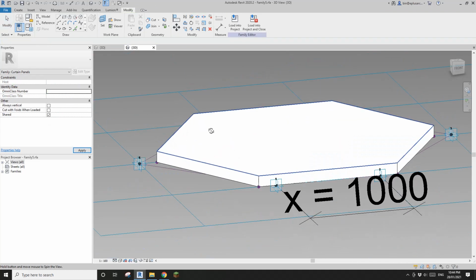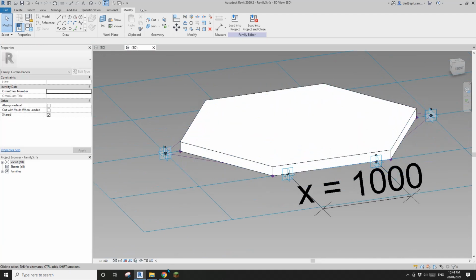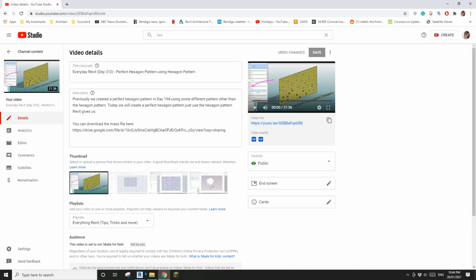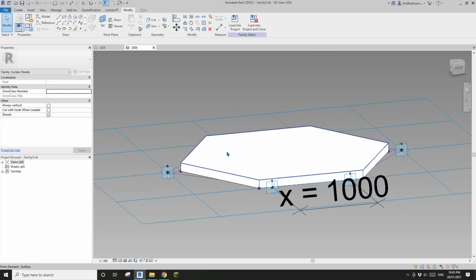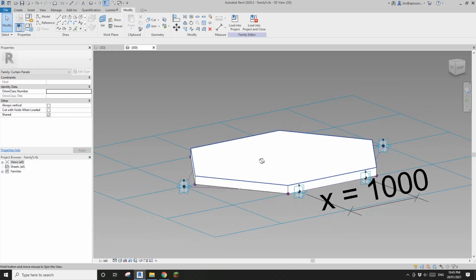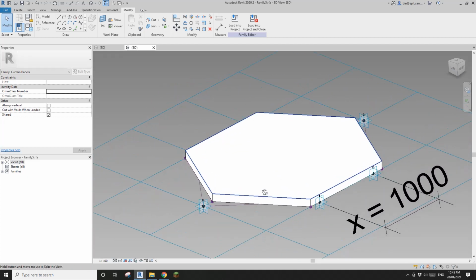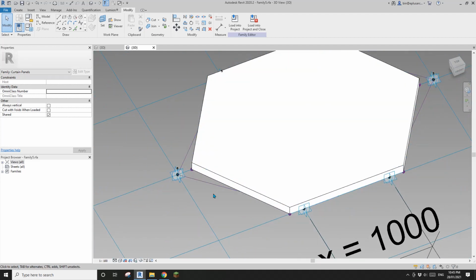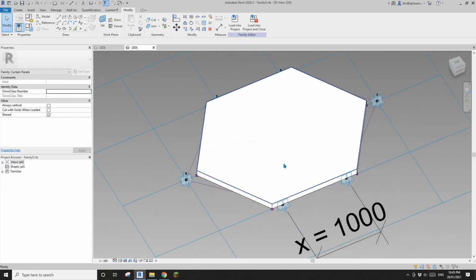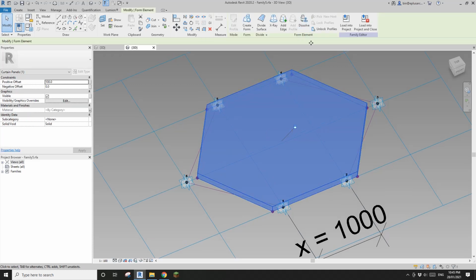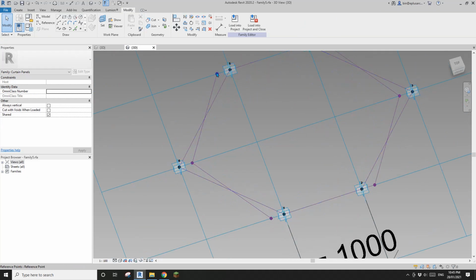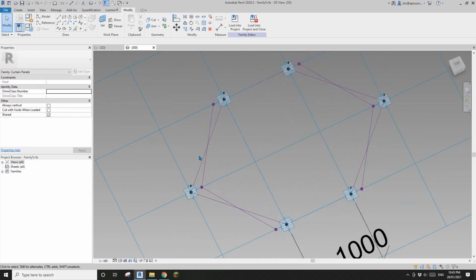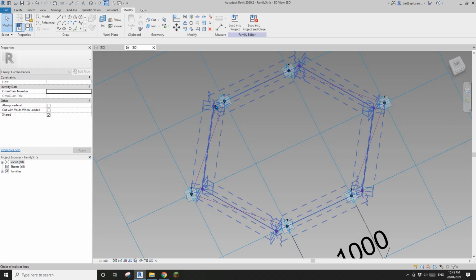Okay, and then last time when I did it in day 245, we offset the point and tried to make it flat, but today we're going to do it slightly differently. First, I'll delete this solid, dissolve it, because this is the shape, and we're going to overhang this panel a little bit. So here, we're going to just offset this point.